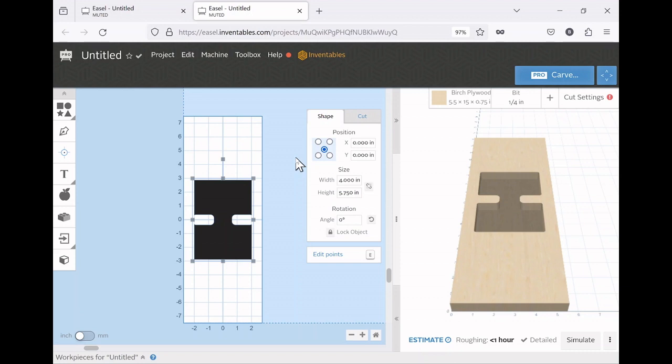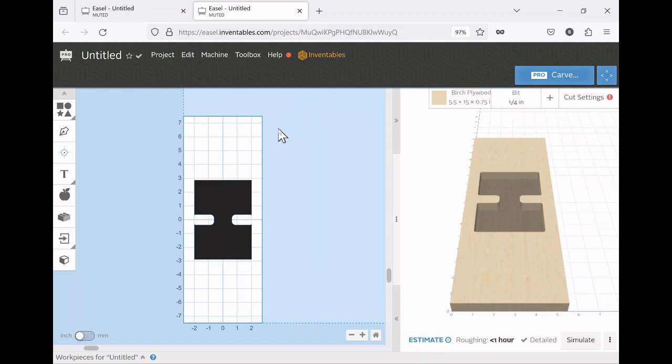And you would have had a rectangle with a couple little bumps in the center here, right here, where we moved it 1/8 of an inch further beyond the border of the rectangle. But since we set the depth of cut to 0, Easel treats that differently. In that case, it does a subtract. So it has now subtracted the two white areas from the dark area that we have here. And the result is one object, not three objects anymore, but just one object.